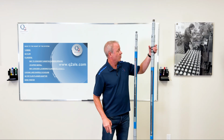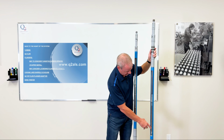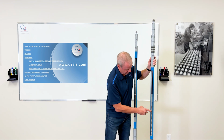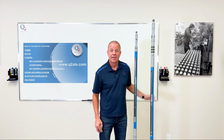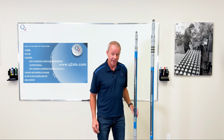But this one here is a top hold down, and you can see in this configuration they have a lot of grooved, and these are grooved plungers here. So this helps too as well, because the sand doesn't come in and score the inside of your plunger against your barrel there too as well. But we also actually recommend certain types of barrels for sand.